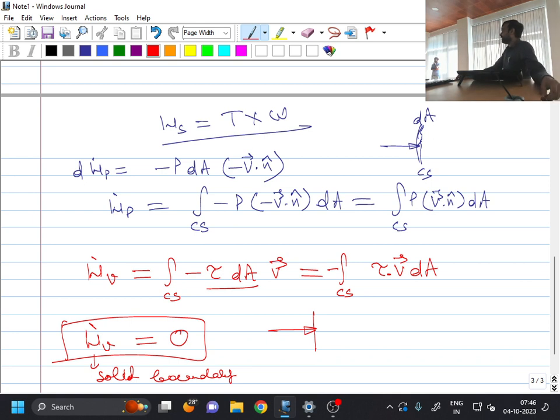Have you attended the kinematics part, where we estimated shear strain? Strain was a second order tensor. So when it is multiplied with viscosity, that becomes nothing but a stress, the viscous stress. That's why this is also a tensor quantity.